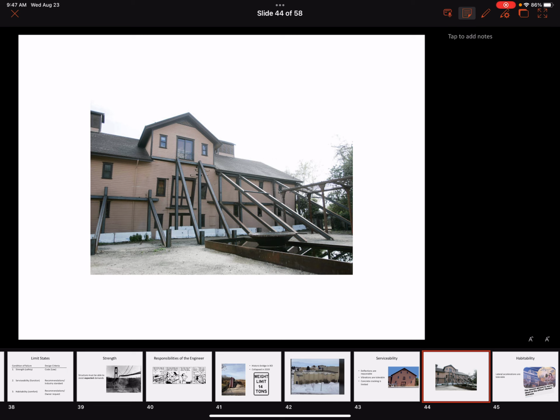at all. In fact, there are a lot of historic structures in Yellowstone National Park that have been renovated to resist seismic loads now. The Old Faithful Lodge is one of them, and they've been done in a pretty thoughtful way. You wouldn't know it looking at it, but they maintained the original mass timber columns, and they just hollowed them out and put some steel frames inside.